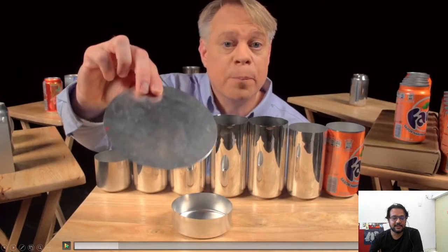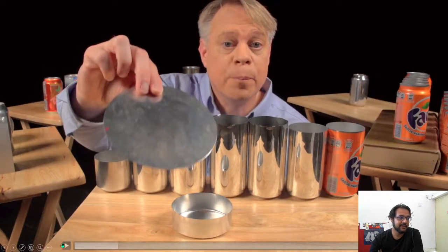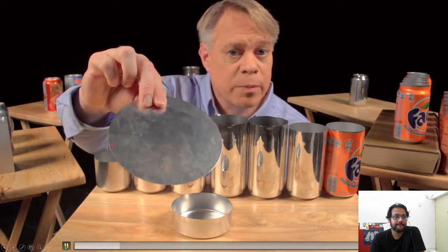So this is the part that we are discussing here, the process of deep drawing. And as you can see, he's made a very nice explanation with the different stages of the manufacturing process, and this is what we were talking about. The first step in the deep drawing process is to create this kind of blank. The blank is just cut out from a sheet of metal, punched from an aluminum sheet about 3/10 of a millimeter thick.